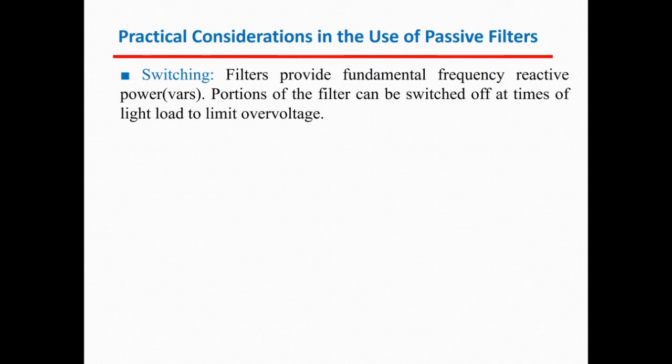Okay, so one function of the filter, of course, as we said, is that they can be used to improve the power factor, since they are providing reactive power. So during light load, the voltage level will normally be high. So if the capacitor remains in the system, that can increase the voltage to a value that exceeds the recommended limit.